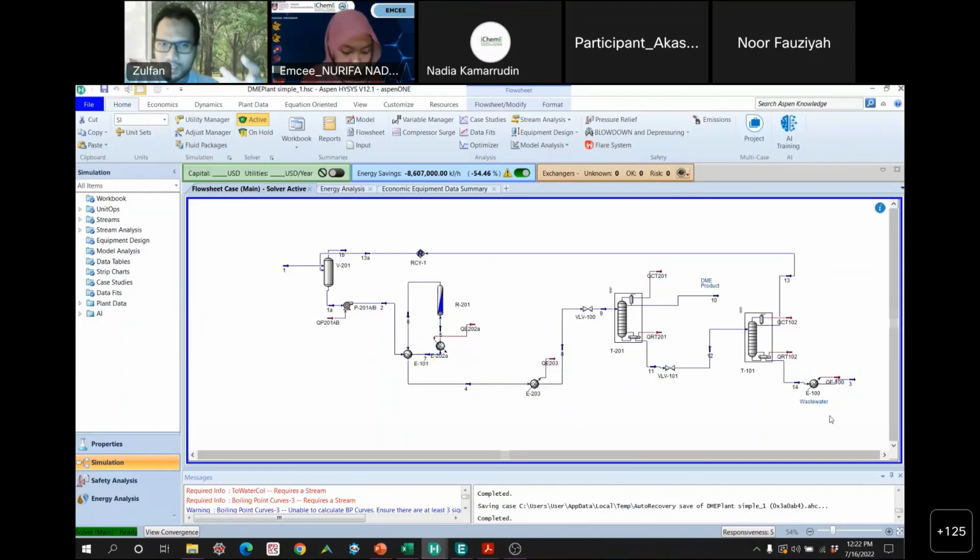So imagine that you have another one over here, and then another one somewhere here. The more complicated the solutions that we give, the more integrated the plant, the more the controllability space is going to be reduced. Before, we could simply open and close the utility valves. There's no controllability limit other than the control valve itself. But the more integrated the plant, the more control system that we have to put in place.